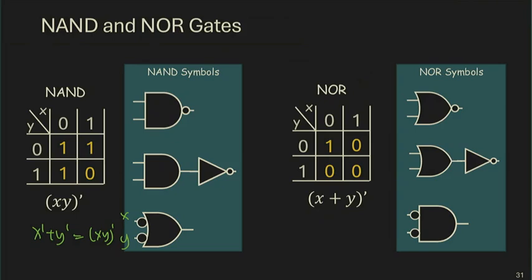Similarly, a NOR gate can be represented as an OR gate with inverted output, or in this cooler way, an AND gate with two inverted inputs. Right? Again, think about bubble pushing. A bubble pushed through the gate becomes bubbles at the other side, changing the gate type. And again, you can prove the bottom one is indeed correct by applying De Morgan.